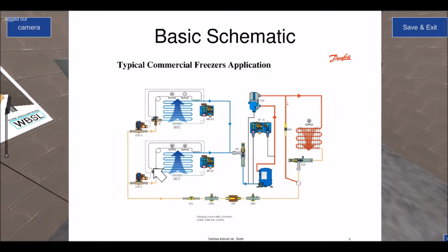This is representing your thermostatic expansion valve. So that's your metering device, if you like. And this little bulb here is measuring the temperature of the vapor, the sensible temperature of the vapor as it exits the evaporator, and that has a corresponding pressure. So in other words, the refrigerant inside that bulb is the same refrigerant that's inside the entire system, and the related temperature will give it the related pressure, and that will push down on the diaphragm, which will force the valve to open, which allows more liquid going in.